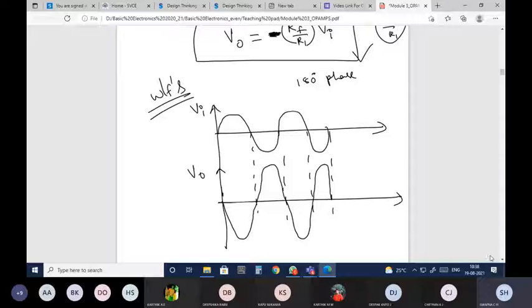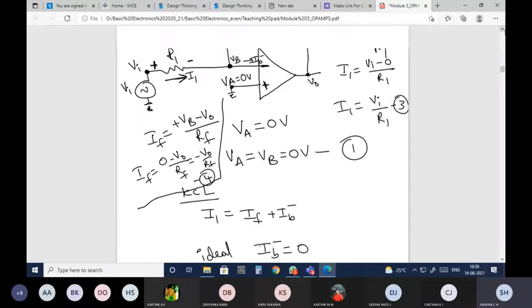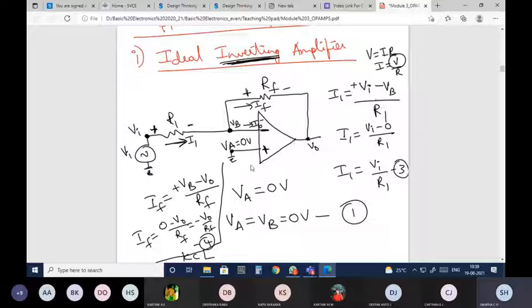Hope this is clear to all of you. Understand one application properly. The rest all will be very simple. Only thing is you need to remember the diagram, and here I've just specified how to remember the diagram as well. First draw the basic op-amp, then RF and R1 will be there. Any circuit you take, RF and R1 will be there. And where you need to give the inputs, you need to check. That's how some additional components will be added to the basic op-amp circuit. So this is how you need to add to make it work as an inverting amplifier.